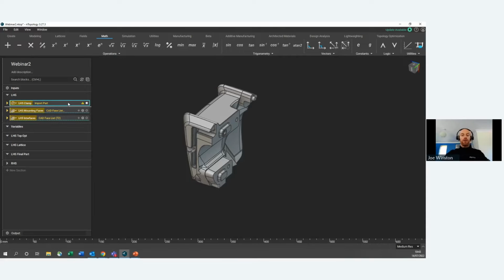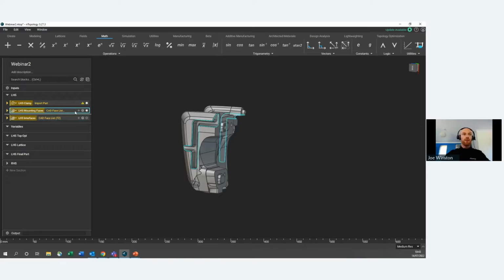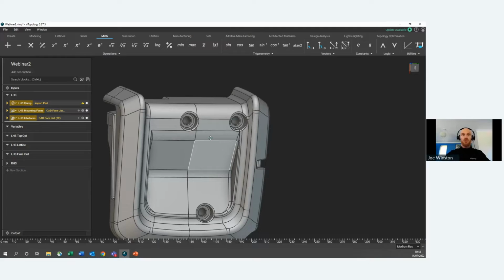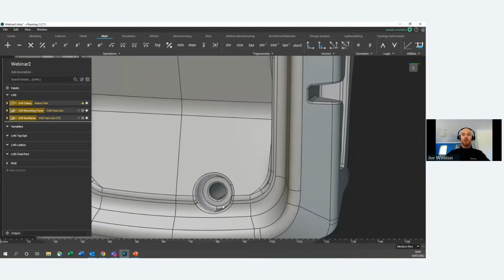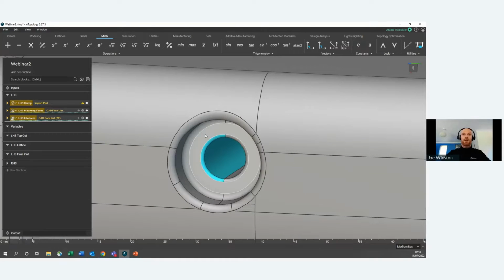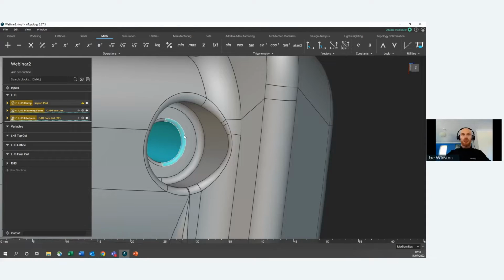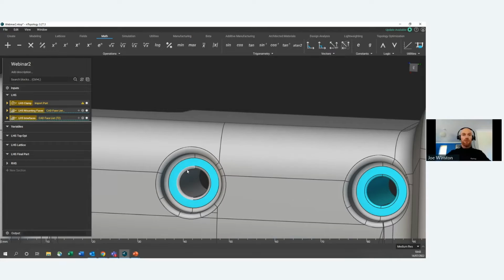Okay, so there are a few extra faces that I'm going to want to keep here. So we've split out mounting faces, split out the interfaces. I'm also going to make sure that I keep these bolt holes. The bolt holes are going to be quite an important feature of the topology optimized part. So all I'm going to do is hold down Control and click all of these faces, just to make sure that we can reuse them a little bit further down the line.